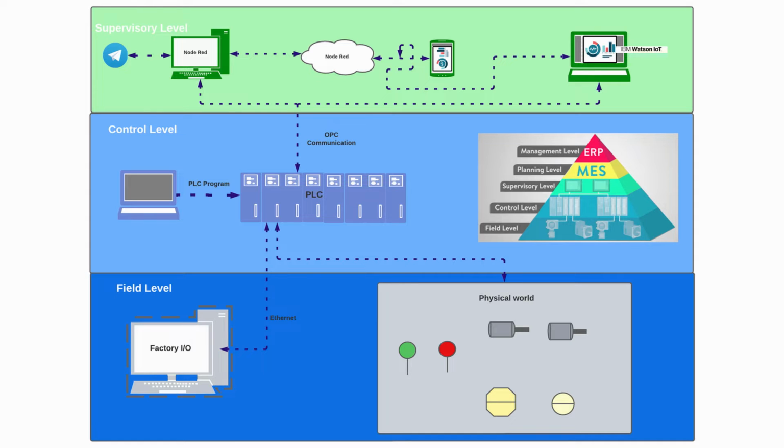And all the information is sent into a SCADA-ish level made with the cloud Node-RED, where all the historicals, alarms and user interface are displayed. There is also a local Node-RED that makes possible command sending and basic monitoring through a chatbot in Telegram. In this project we will use Telegram to send basic commands to our logic and receive basic status. And the cloud Node-RED with the dashboard, which includes the user interface, will be reachable from any computer or even phone, from where we can see and send all the information necessary.